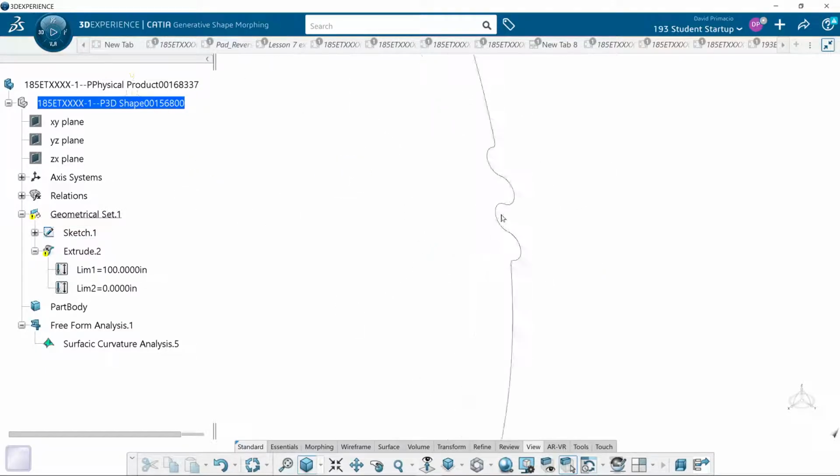You cannot have this happen. And I know you look at it and think, oh, there's no way someone would make it like that. Well, they do it all the time. Again, the main reason that happens is because they're given point coordinates to work with, and they make the curve go through the point coordinates no matter what. You really shouldn't do that. You should be trying to create a curve and let the surface or the spline develop the best, smoothest curve it can create based on your points. All it's going to do is fix your miscalculation of your location of your points. And that's how that really should be done. Okay?